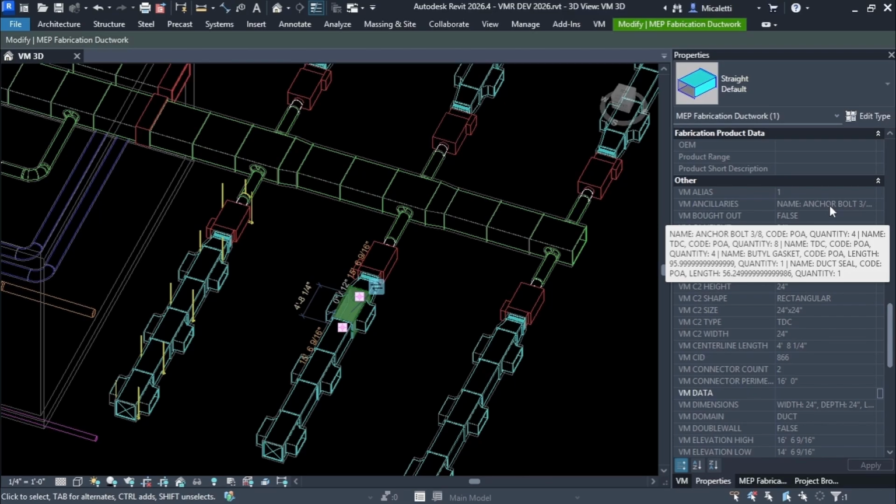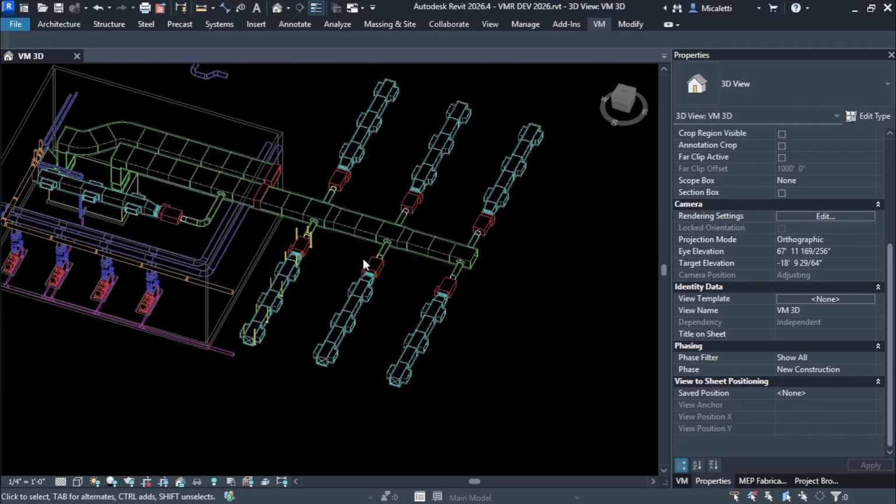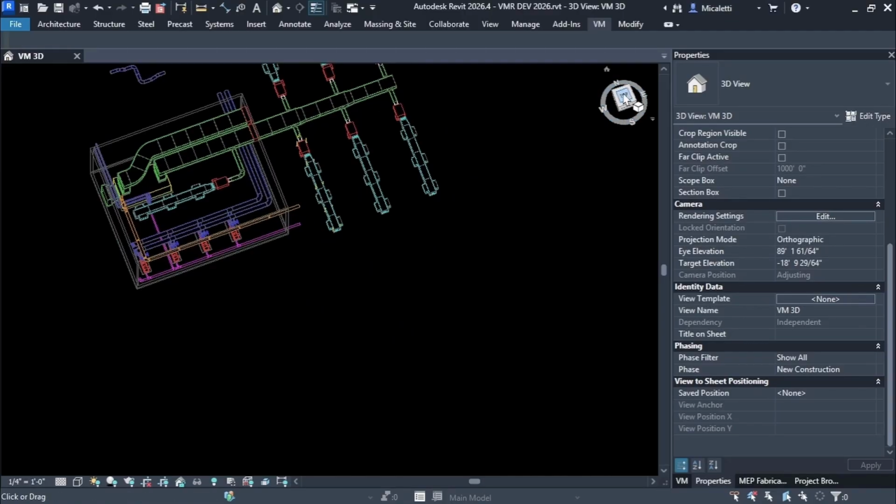Sorry to interrupt, how do you reformat, like, so that's something I've seen, and it's almost a base Revit issue in the sense of ancillaries. There's just a really long string, right? So how do you get a Revit schedule to break that out or format it in any way other than just that long string? That's a good question.